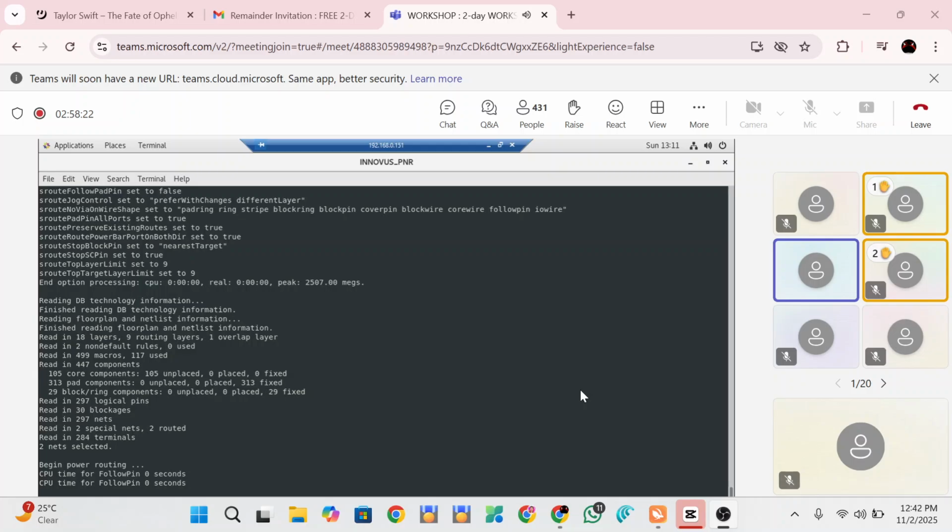Let's say you have 20 metal layers, M20, just let me finish, please. You have 20 layers. The power has to come from the top metal layer down to the bottom metal layers with a mesh. A mesh goes vertically and horizontally through the metal layers. So what is the top metal layer for this technology? What are the total metal layers? We have 9 metal layers. We have to analyze whether that mesh is created from top to bottom or not.